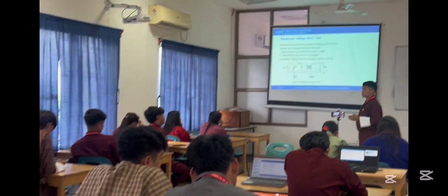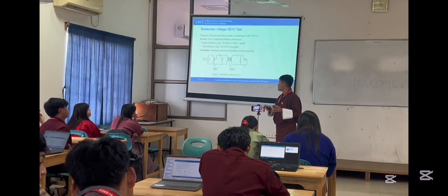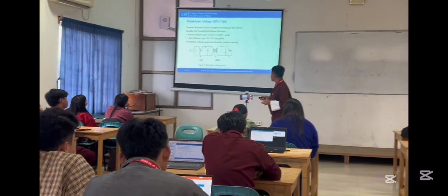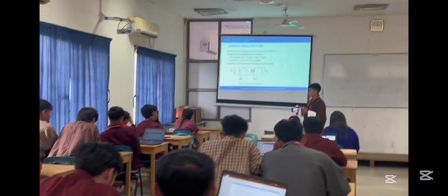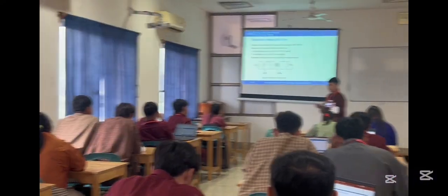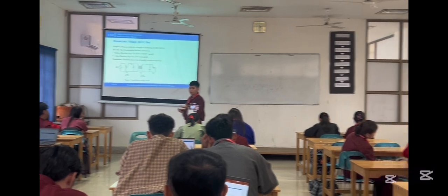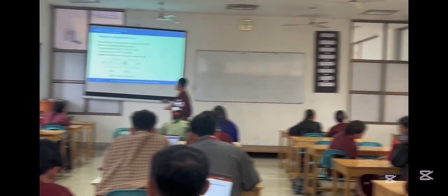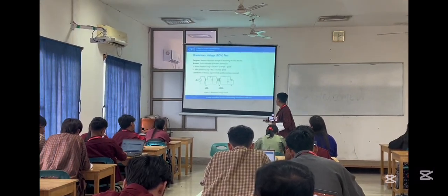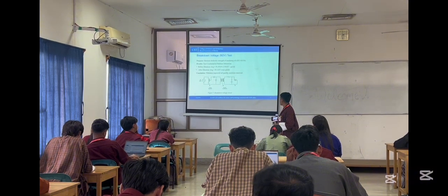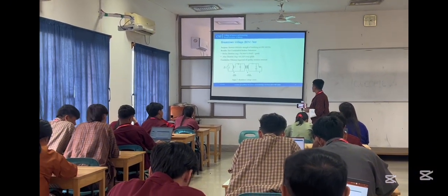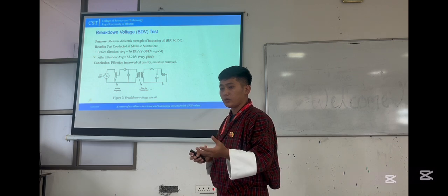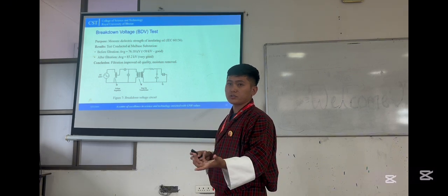As we all know, the oil is a vital component of the transformer. So to determine the performance of the transformer oil, we do the test. The test area that we have is Malwa substation. Most recently, the Malwa substation has changed the transformer. So there we have done the BDV test, before filtration and after filtration.